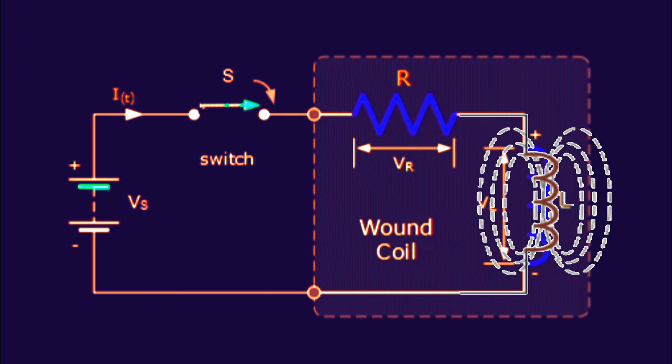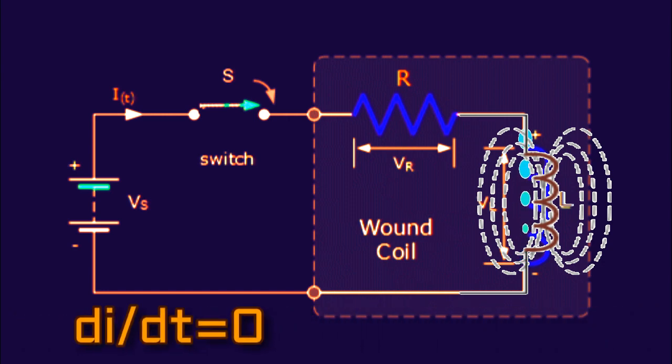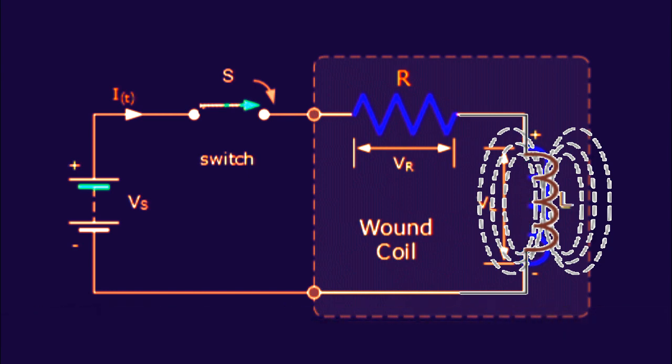The current which now flows through the coil is determined only by the DC, or pure resistance of the coil's windings, as the reactance value of the coil has decreased to 0 because the rate of change of current is 0 in a steady-state condition. In other words, in a real coil only the coil's DC resistance exists to oppose the flow of current through itself.